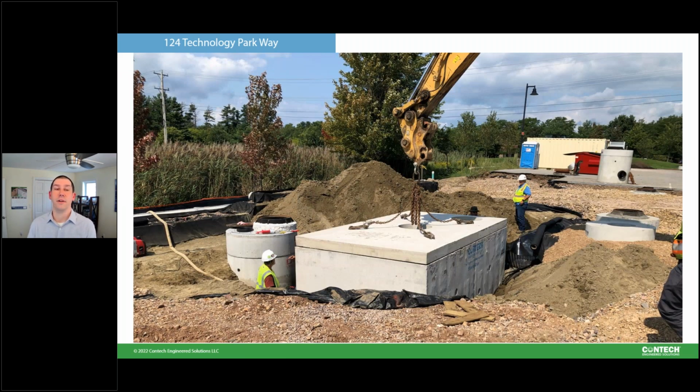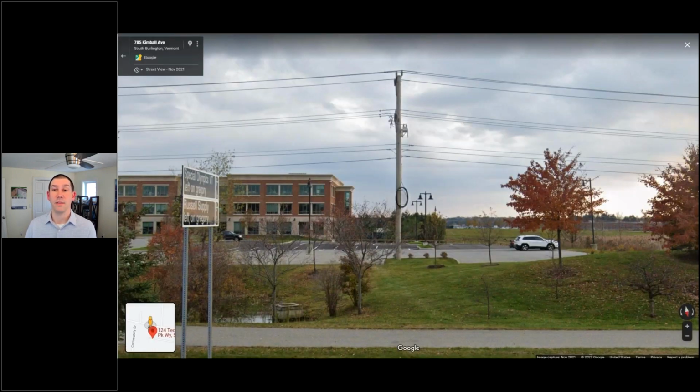And so you'll see, here on my next slide, I don't know that it's popped up for you guys yet, but there is a site install. The contractor is actually standing on top of the detention system, peeking out. The system itself, the detention, arrived on site about a week and a half before the storm filter did. And because the contractor was familiar with it, he went ahead and just installed the entire system before the storm filter arrived, which subsequently made things very simple and easy on site for the storm filter install, because they had a place already prepped for it, as you can see here. And that certainly made finishing up the construction a much less challenging situation because they were ready to roll.